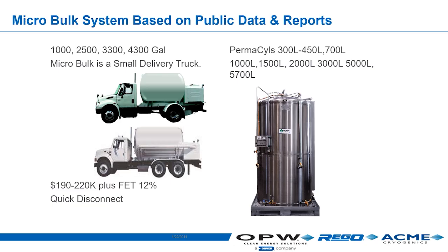Those were originally the 1000 and the 2500, and then they just supersized a liquid cylinder into a microbulk. Everybody sells microbulks now, and microbulks have gotten huge. For liquid cylinders and microbulk, the unit of measure is always going to be in liters. So if it's silver looking, it's in liters. Once you get into bulk tanks and bigger, it now goes to gallons.